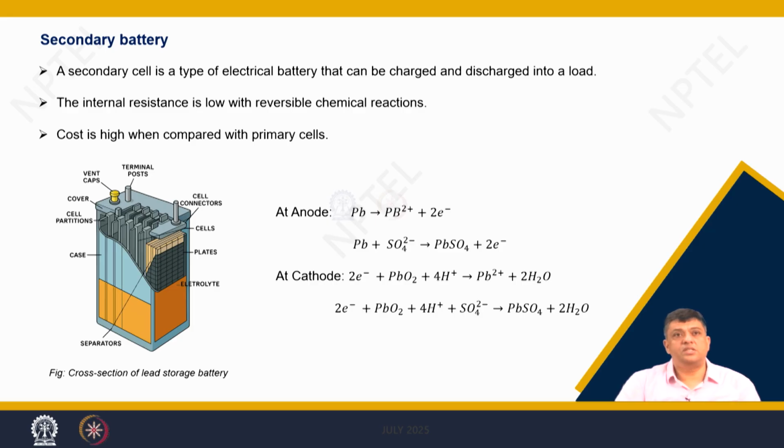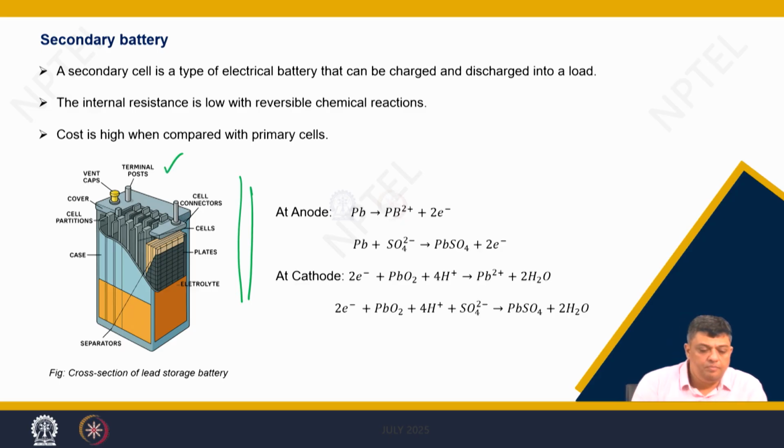In secondary batteries, for example, one of the most used batteries, let us say a lead acid battery, you have an architecture which has a large number of cells attached together to give you a battery, and you have lead plates and electrolyte filled in between, and then you have the cell connections and the terminal posts which are put inside a cover.